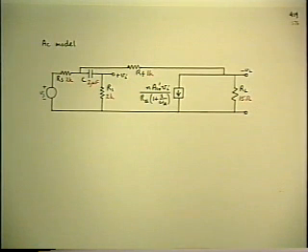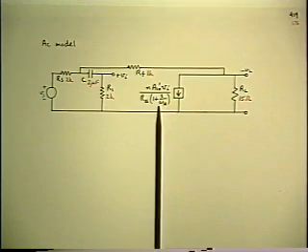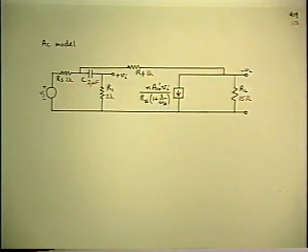The purpose of doing that was that if you put the capacitor in immediately, then you have some algebra to do to get the result in factored pole zero form, whereas by ignoring the capacitor, that is replacing it by a short, we were able to get the mid-band value of the loop gain very easily. Then we restored the coupling capacitor using the extra element theorem, and that gives an inverted pole at 30 hertz at the bottom end of the mid-band loop gain, and then you restore at the same time the normal pole, which is part of the forward path, and that pole is at 2 kilohertz.